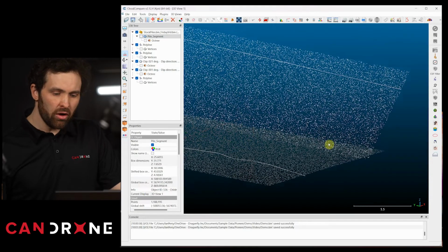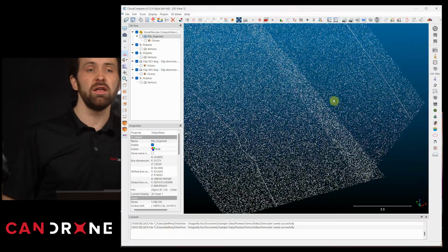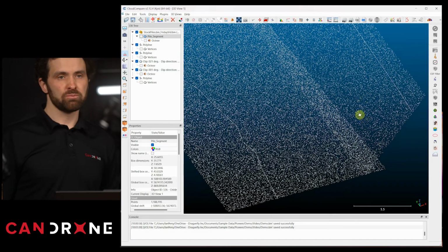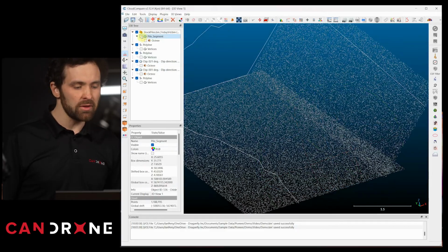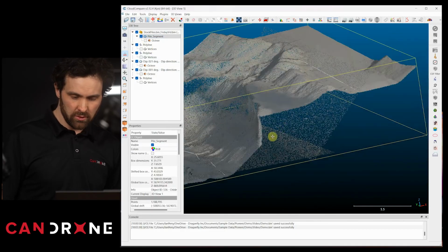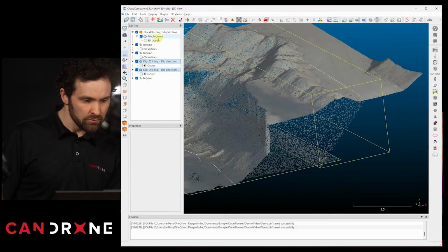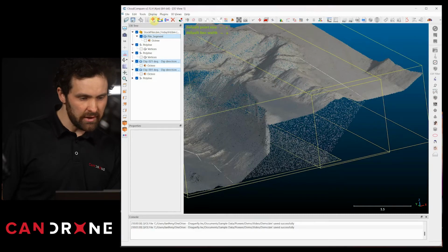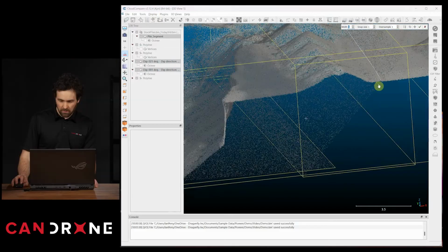Let's do the same thing on the other side. This will be the last wall we have to create before we have a fully enclosed volume to use for a volumetric analysis. Turn that top cloud back on. Highlight all three clouds. Engage the tool Trace Polyline by point picking.